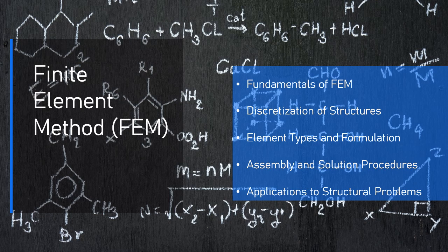4.4. Thermal stress analysis. In many structural applications, temperature variations can induce thermal stresses, which can affect the overall stability and performance of the structure. FEM is commonly used to model thermal stresses in structures that experience temperature changes, such as bridges, dams, pressure vessels, and piping systems. Application example: analyzing the thermal expansion in a pressure vessel subjected to heating and cooling cycles, which could lead to thermal stresses and deformation.